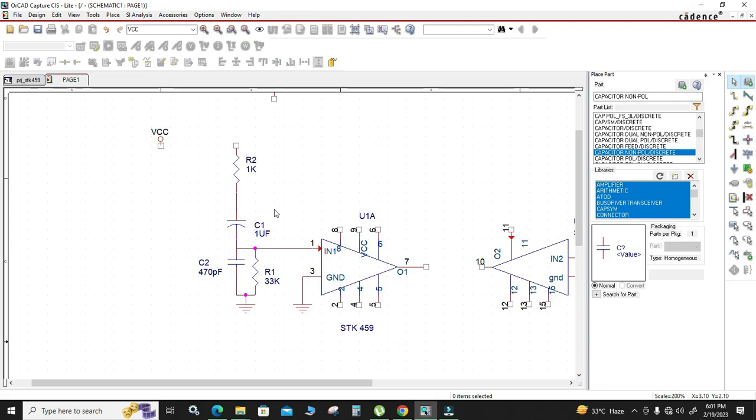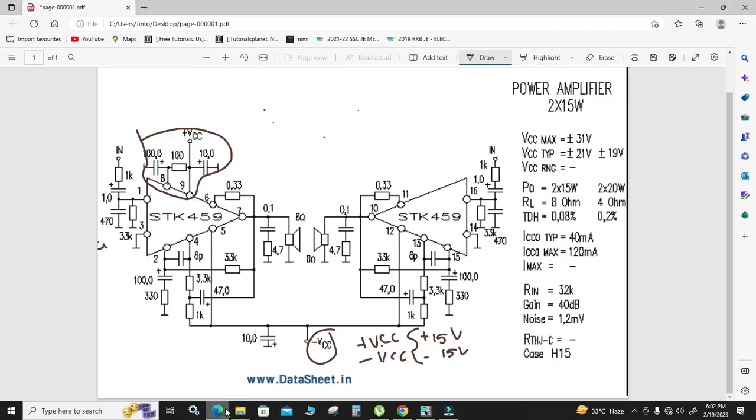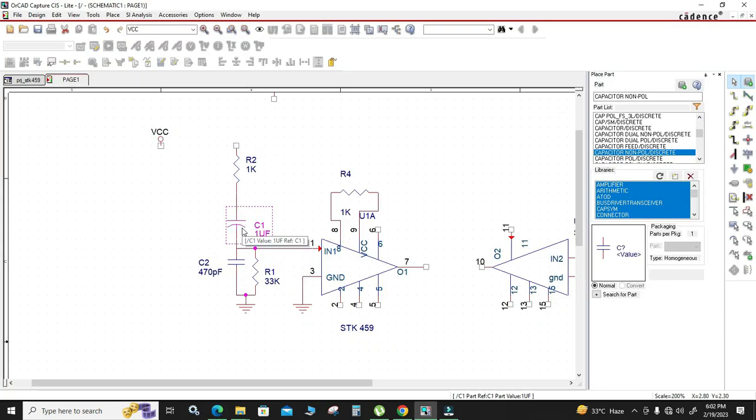8 and 9. Okay, you take these copies again, and to rotate it, press control and the R button. 8 and 9 across, then press W, choose wire. 8 and 9 across like this. Then two polarized capacitors go across the circuit. So we choose a copy of this one, then rotate it. The straight line is usually used for the plus portion, and the curved one is negative. So connect it to the wire.